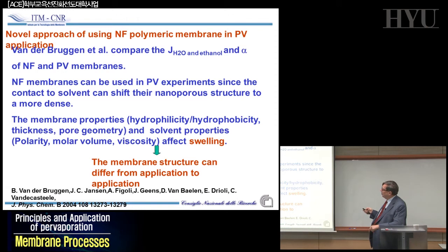In nanofiltration, what you have normally is very low rejection for monovalent salts, sodium chloride, potassium chloride, and similar, and much higher selectivity for chemical species having higher molecular weight, 100, 200 Dalton, 300 Dalton, 1000 Dalton, this order of magnitude.